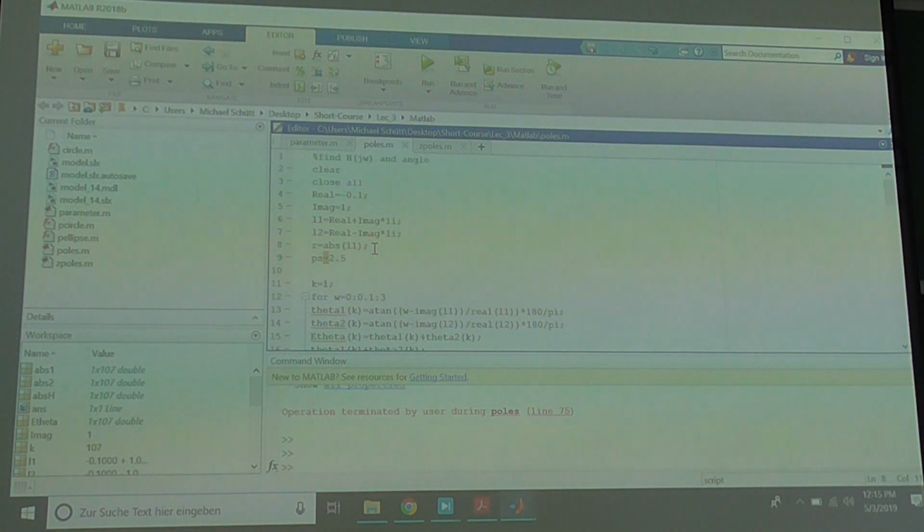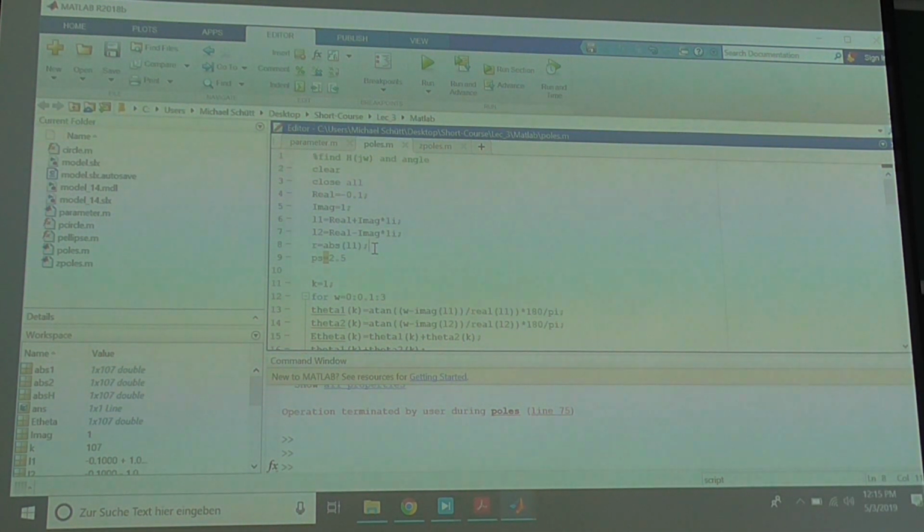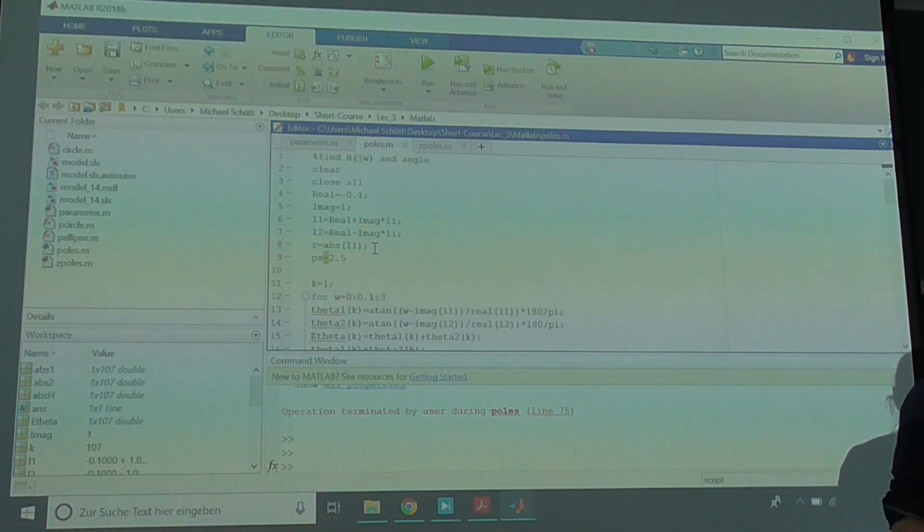So they just assume they can use a certain equivalency for the integration. For instance, Tustin says this would be Ts by 2, times 1 plus z to the minus 1, over 1 minus z to the minus 1. And they just use this to replace the 1 over s.